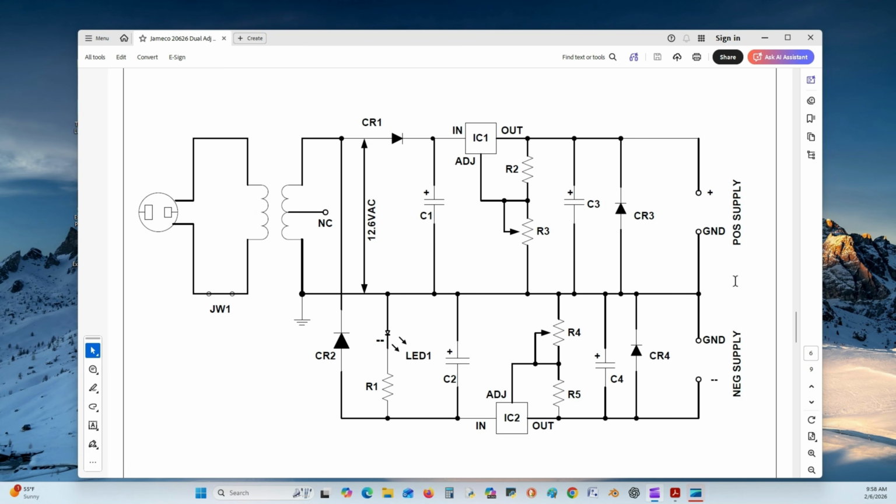Welcome to Tech Talk 130. Here we're going to be using the QUCS simulator to build and simulate the power supply we just constructed. As you can see here, we're going to have an AC step-down transformer from 120 volts to 24 volts AC. To make our pulsating DC, we're going to have our 1N4001 CR1 and CR2, making a half-wave rectifier.